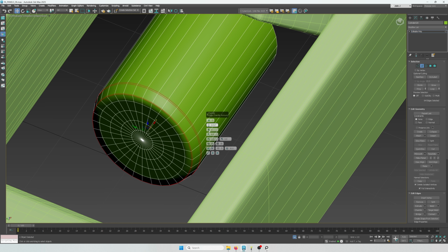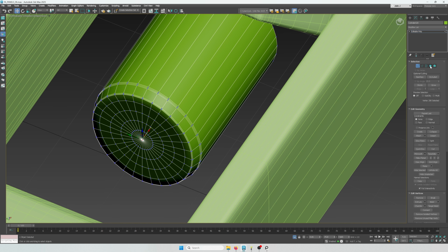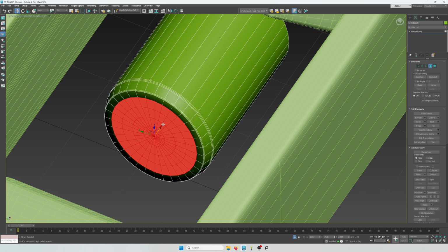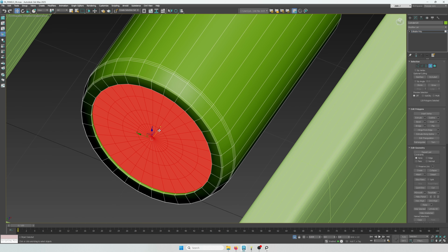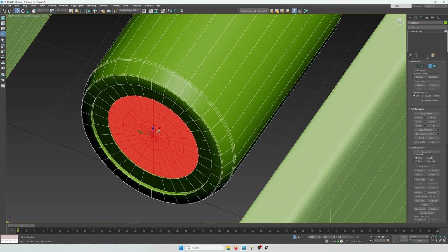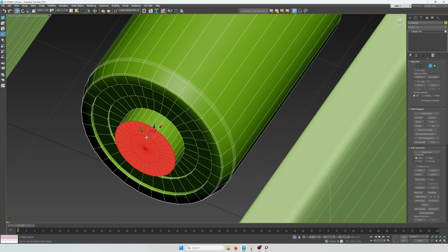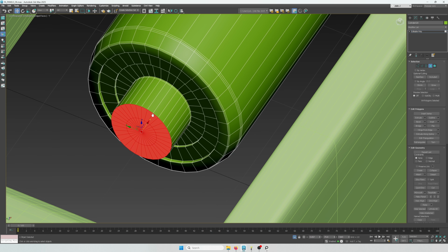We're going to leverage the fact that we have many lines here to use movements, insets, extrusions in order to shape the details in this area. And we do this by selecting the center and expanding the selection, then extrude it in a little and extrude it more. Then you contract your selection, extrude it a little and then more. Contract it, then extrude it out, and then again. No, undo that. Extrude it a little first and then extrude it more.